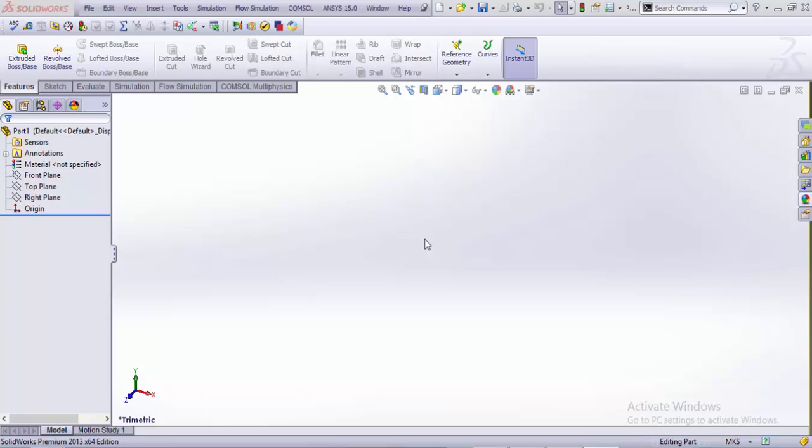Cams can be classified depending upon various elements, like the surface in contact, which depends upon the type of the follower. The followers are of many types, like knife edge followers, roller followers, spherical faced followers, flat faced followers, or some other types as well. But in most applications we mostly see roller followers or spherical faced followers, since they produce a lesser amount of friction.